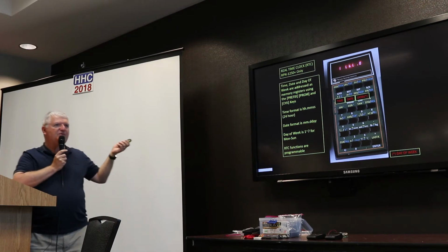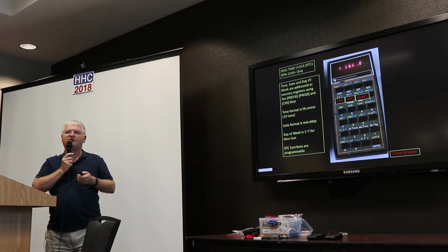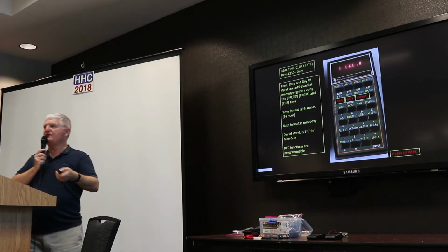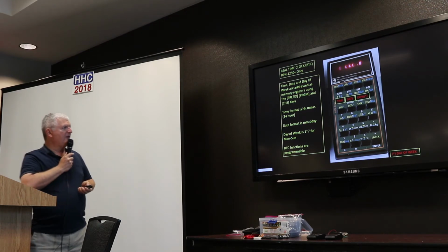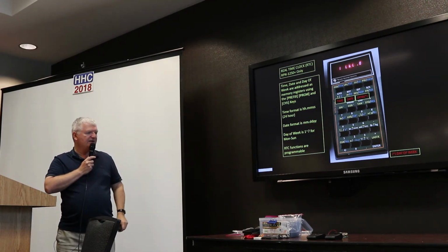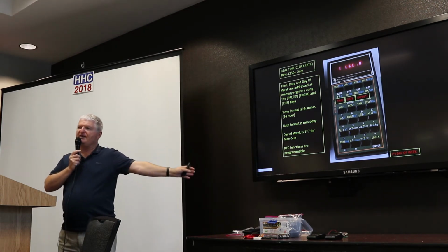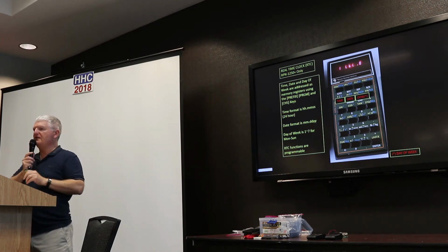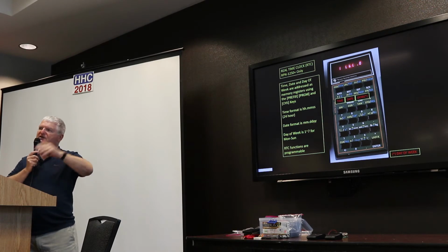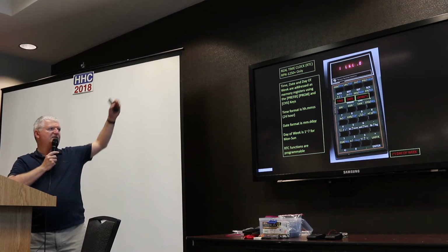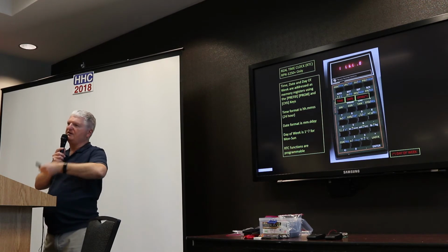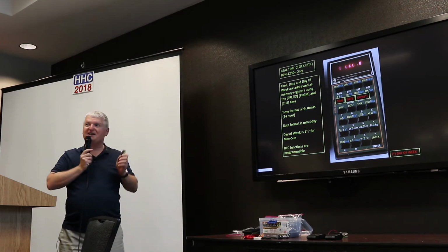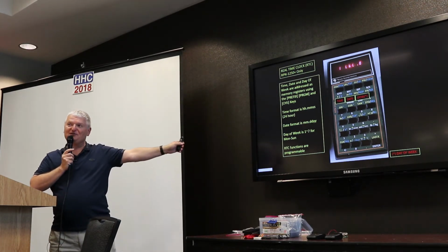Okay, and for the 1250 Plus, I put in a real-time clock, so it's addressed with store and recall functions. You can recall time, recall date, recall day of the week, or store it to initialize the clock. On top of that, the real-time clock is addressed with an I2C bus. So it's 2 lines, and you have power and ground. And I took these lines also to a connector area so that you can wire something outside of the machine and address a peripheral if you want. This being said, you cannot program the I2C functions yet from the keyboard.